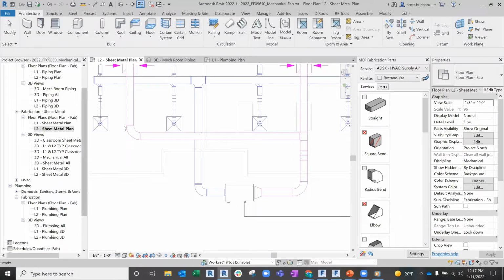Thank you. Okay, so it's going to look at all of these that are available and say, hey, what fittings can I use? So if I look at why did it not use a mitered bend there, it's because I have that being excluded when it does that conversion. So that's why it went to the next bend and put that inside of there. So as a shop owner, as I'm building this out, I get to define what fittings get used inside of here, right? So that's going to be the rule there.